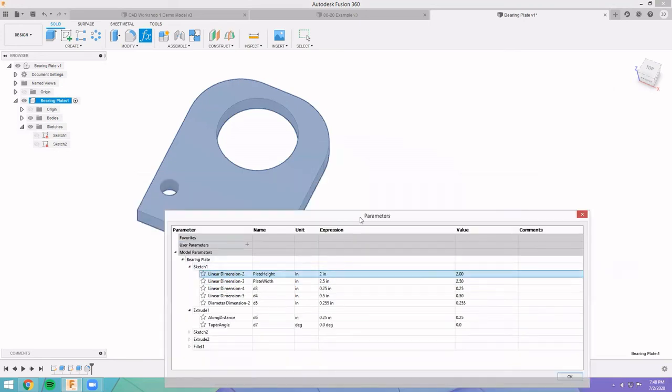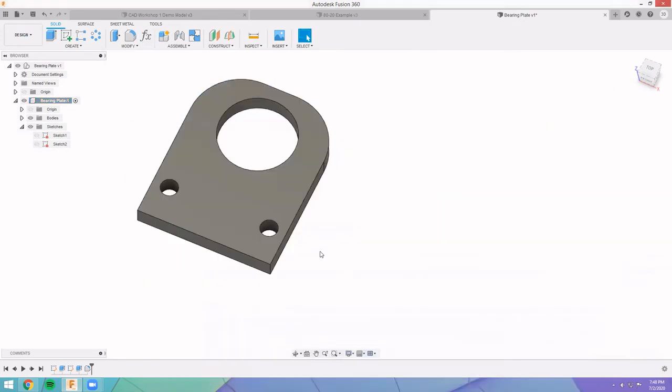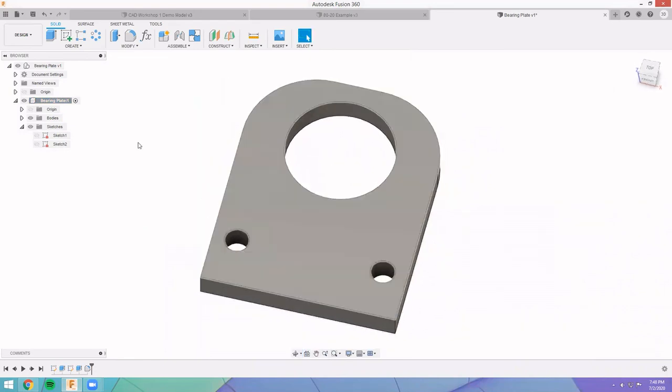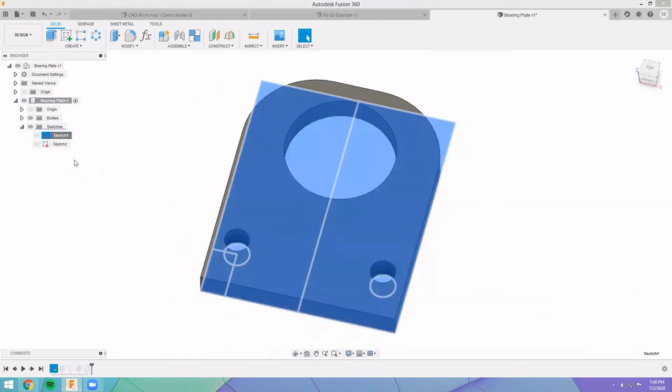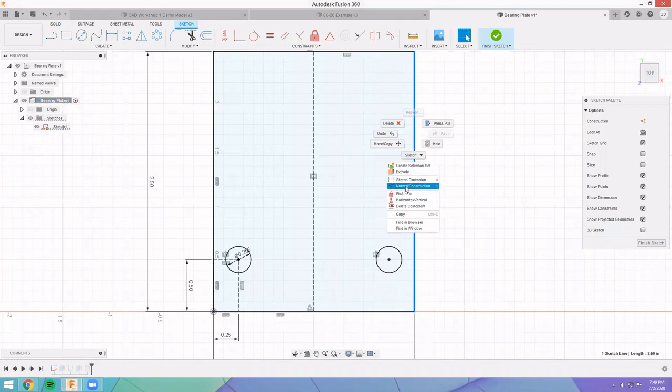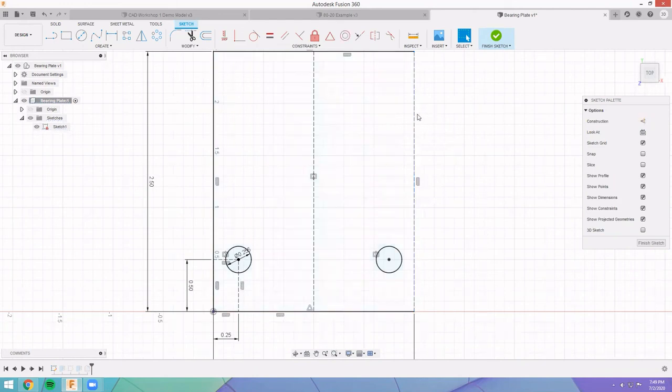And then one last question was, what did you do to turn the sketch lines into construction lines? Let's go back into that sketch for a second. Any line, if you just click it to highlight, you can either right click, and then there's the toggle for normal / construction, and the shortcut for that is just X. So if you click and do X, that'll be a construction. Click and X, and that's a normal line. And that works for any amount of lines. So if you double click to get the whole polygon, you could make the entire polygon construction or not construction.